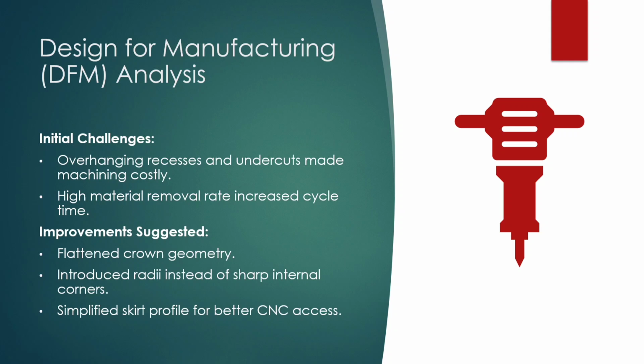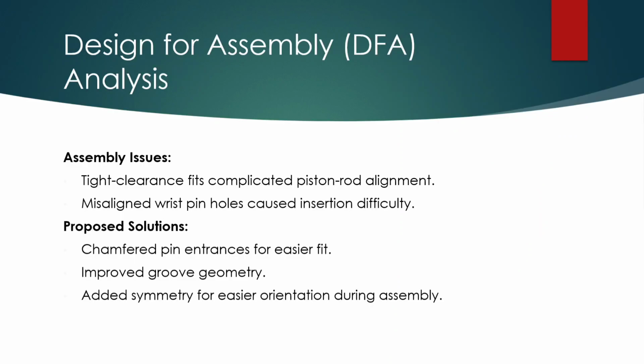Next slide, please. So the design of our assembly analysis is something we have gone through theoretically, what we will assemble and how we're gonna do it. This is a very big engine, so we have done the piston CNC operation just to make sure that we know how to do it. Tight clearance fit and complicated piston rod alignment, we have corrected to make sure that the engine can run smoothly. Misaligned wrist pin holes caused insertion difficulty. We also minimized those problems as well.